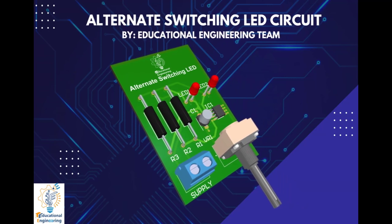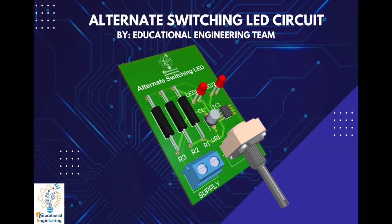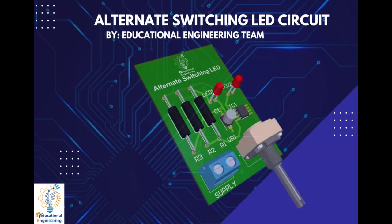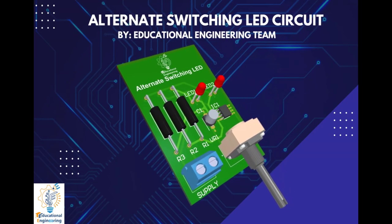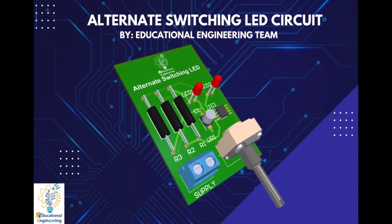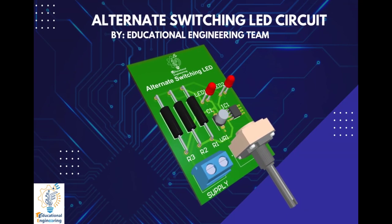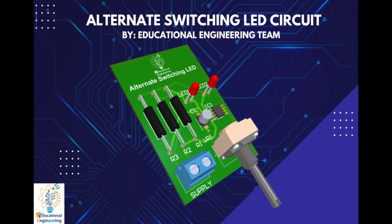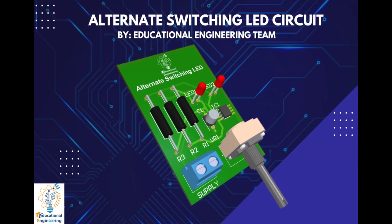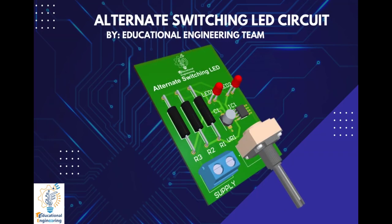The square wave output from pin 3 was used as a source for LED 2 and sink for LED 1, thus making it perform a switching operation. Whenever the output from pin 3 was high, the LED obtained source current from the IC and switches on. When the pulse was high, LED 1 will not be grounded and hence it remains in off state. When the output pulse goes low, LED 1 will be grounded to pin 3 of the IC 555.